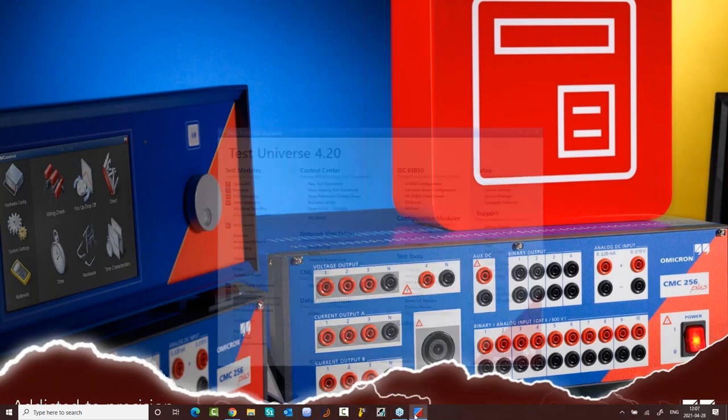Why is REF 615 a voltage actuated relay through its REF protection, versus differential protection? How is it tested? Mr. Sumit, maybe I can share my screen with you. First of all, REF, as I know, is feeder protection. It's not related to a differential, but maybe you mean RET 615, which is the transformer differential from ABB medium voltage. I will share my screen to show you such kind of application, how to do it.